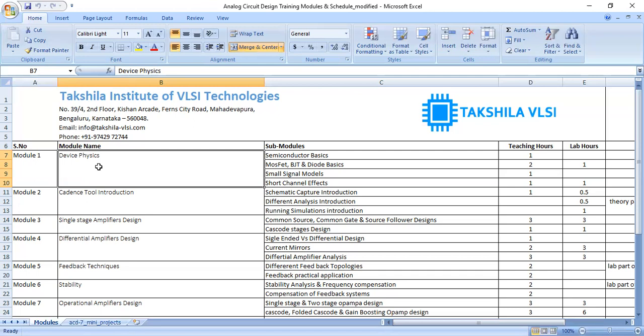This is a very important topic, the small signal model. Whenever we use a MOSFET as an amplifier, we are not dealing with very large signals. It's very small signals, in the range of 1 microvolt, 10 millivolt, 1 millivolt peak to peak. How exactly do these devices behave for those small signals?